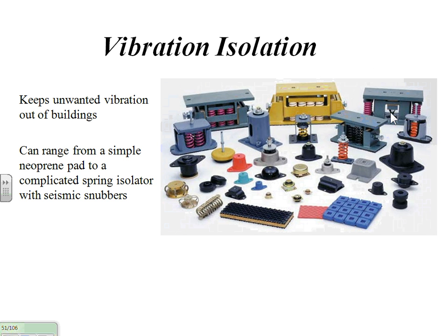These springs are used primarily on big sets where the skid is solidly mounted to the generator, engine and alternator. To isolate the vibration from the pad, we need an external isolator like this. So the bigger sets get typically the springs.